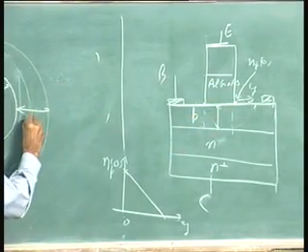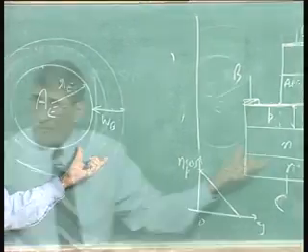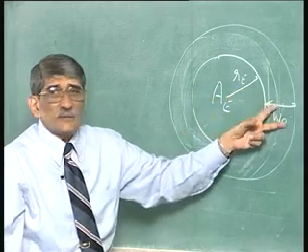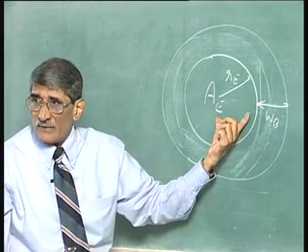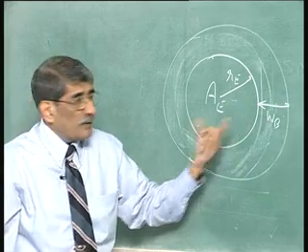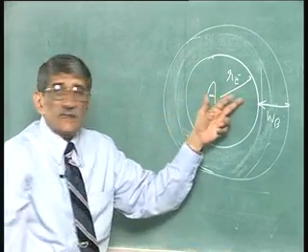So, that is the base width. So, you are trying to find out the surface area over which recombination takes place, that is actually equal to pi (Re plus Wb) whole squared minus pi Re squared. That is AS, and area of the emitter is pi Re squared.